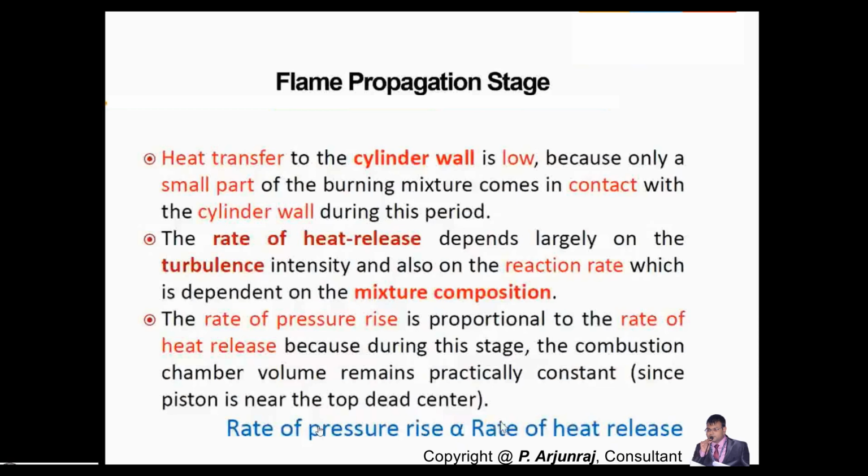Whenever the heat transfer is going to be higher, it may lead to lesser thermal efficiency of the engine, because you should retain some heat. This is a very important stage where you need to retain the heat. When the heat loss is lesser, the efficiency is better. We have seen a lot of losses like blowby loss, friction loss, heat loss, and pumping loss. So the lesser the heat loss, the better the efficiency. If you lose heat in these stages, your efficiency or output gets impacted.